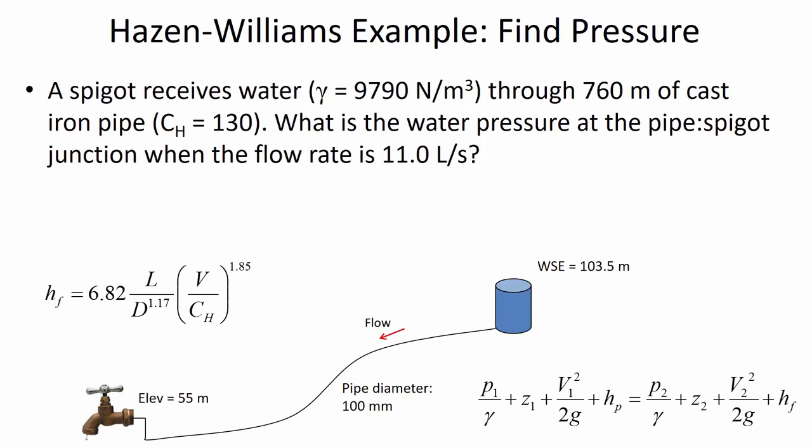And so we have to think about where the energy is going. The energy at this tank, at the origin, is potential energy, and it's causing pressurization downstream, and it's also giving up energy to losses. What the Hazen-Williams equation, which is shown here, helps us to calculate is the losses side of things in an easy, direct way.